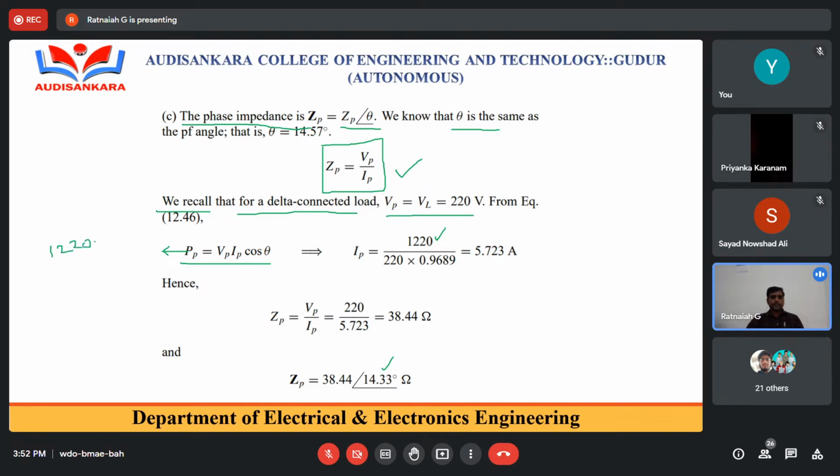So 1220 is equal to V phase, which is 220 volts, into I phase, which we don't know, into cos theta. What is cos theta? That means 0.9689. That is already calculated. Then what is the required value here? I phase. Therefore, I phase is equal to 1220 divided by 220 multiplied by 0.9689.